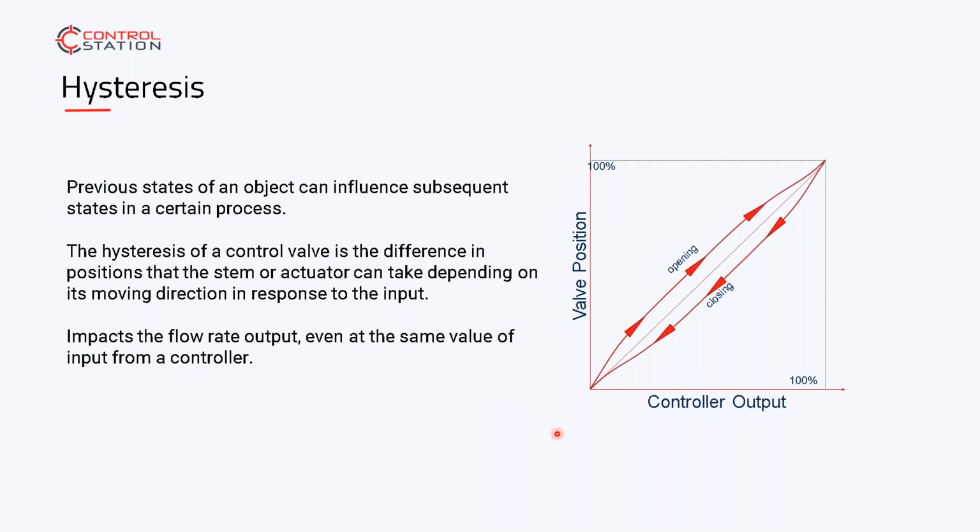It can be very useful to understand what's causing this. And then in the other direction, are we getting the movement but we're not getting the flow change? Are we not getting the movement and we're not getting the flow change? Or are we not getting the movement at all until it takes a couple of steps to do it? All of those will give you that information. Not always possible. Restricted environments, locations of instruments, insulation, all of those things can prevent that in-person understanding of what your mechanical problems are.